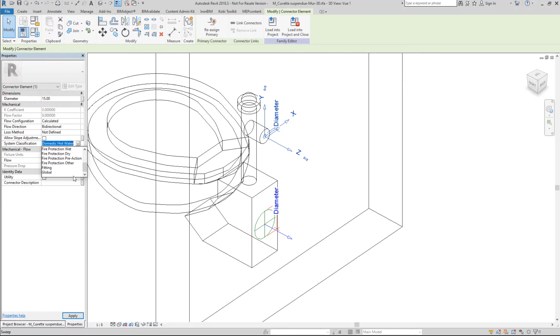Fire protection is self-explanatory, it's for sprinklers, fitting for fitting, obviously, and global. We should also avoid using that one, but sometimes it has to be used, for example, for valves. Usually they are done as globals, or maybe sanitary accessories are done as global. But mostly the most interesting ones for sanitary will basically be domestic water and sanitary.